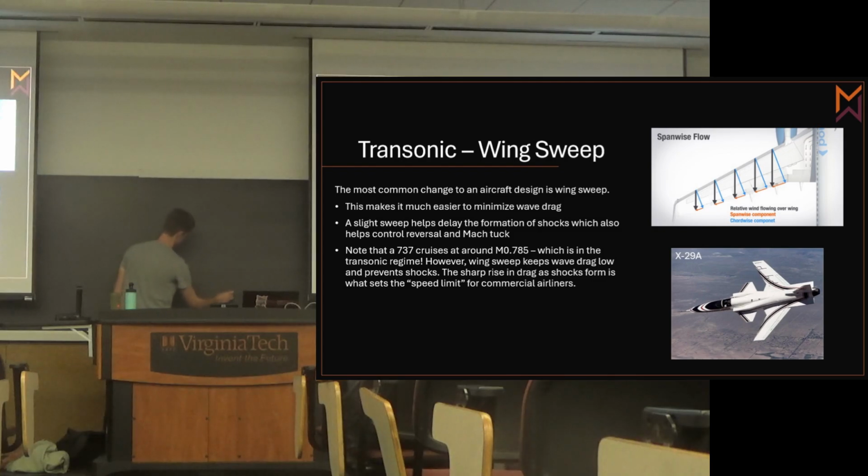An airfoil that you have to get a big speed increase to go over the top, versus this, much lower speed increase. So as I decrease that thickness ratio, it should decrease the speed increase. It's a lot of increases and decreases. But sweep keeps us from building normal shocks, it delays it.